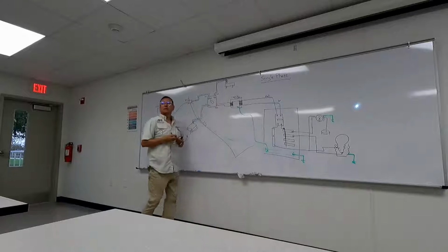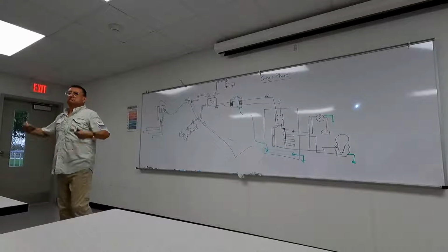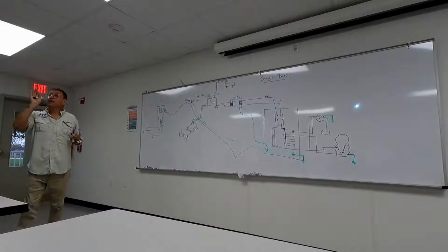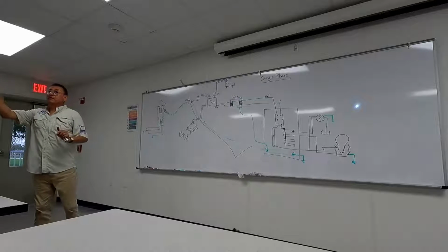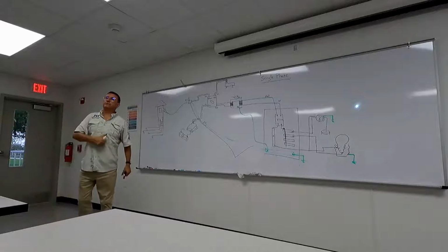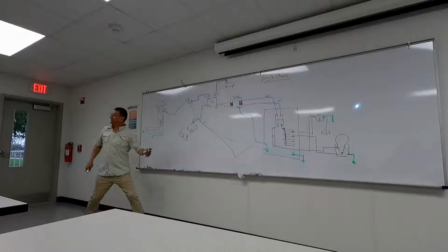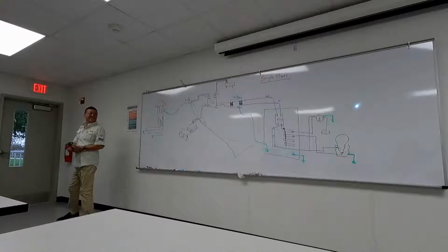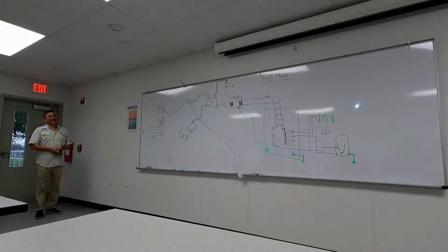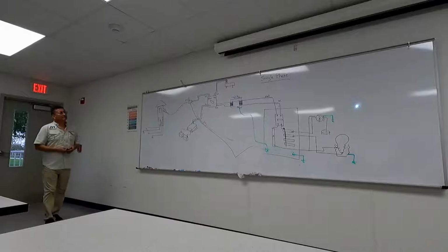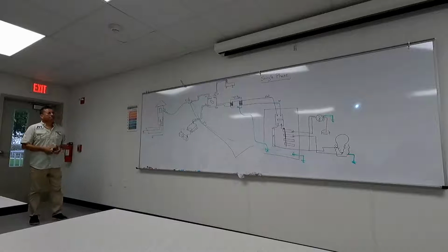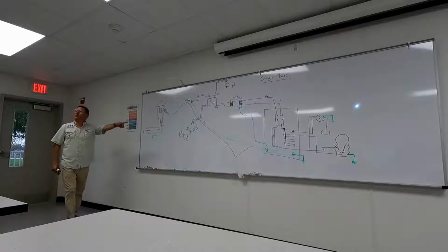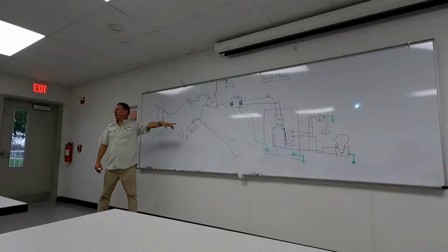How many ground bus bars are there usually? As many as you want. The recommendation is to connect all of them together. Mr. Lopez, can I take a picture? Don't connect the negative on the AC side directly to the battery ground. It will be connected to the ground, but separately. Good? It's clear? No questions?